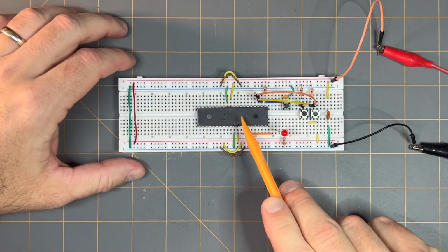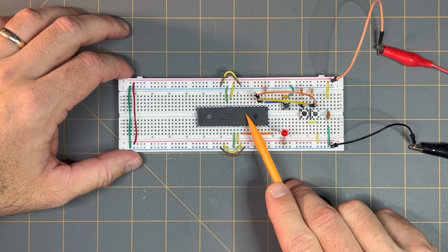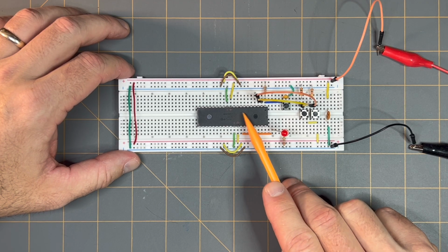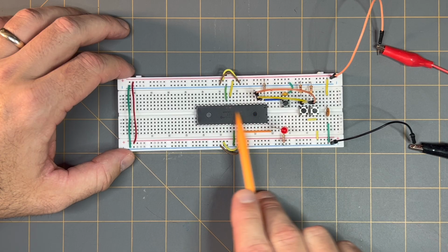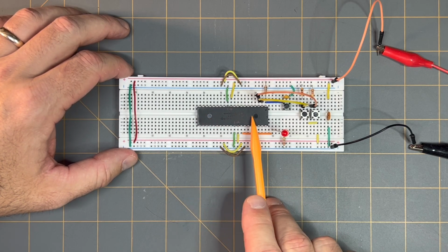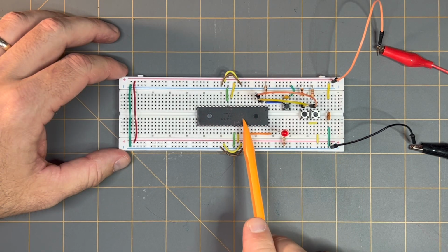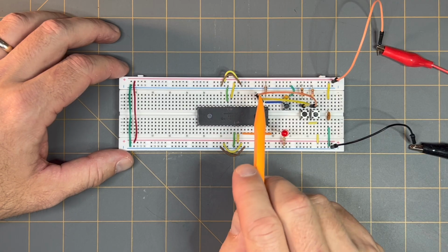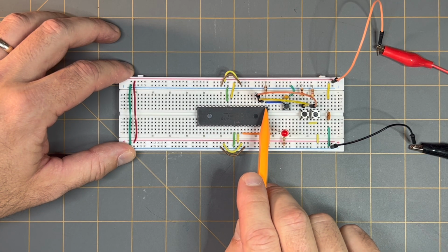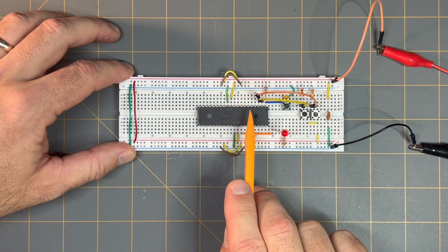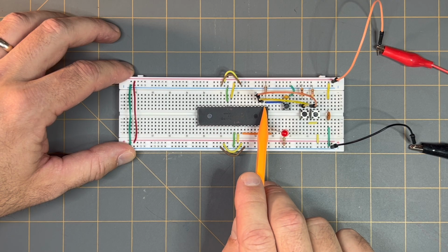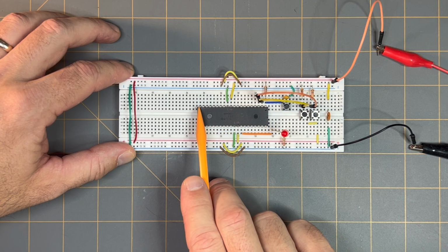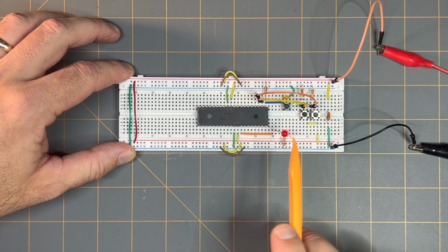As for placing the PIC microcontroller down onto the breadboard, I happen to have placed my PIC microcontroller somewhat in the middle of the breadboard here, and I've aligned the PIC to be about center, and I've placed pins 1 through 20 in the points D22 down to D41. Those are the points on the breadboard.